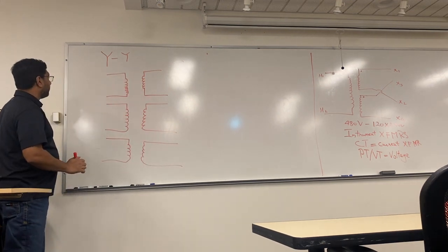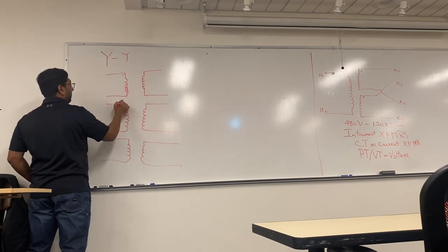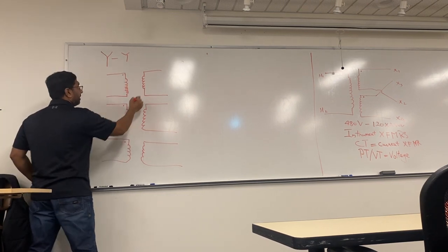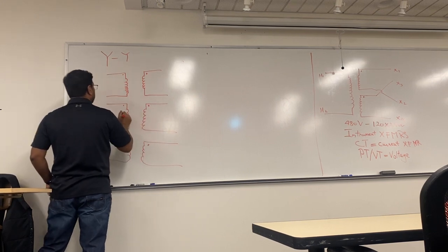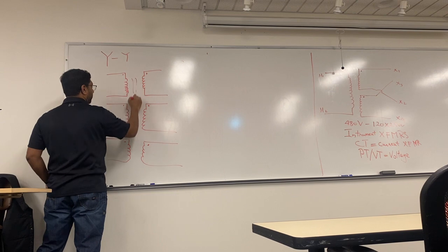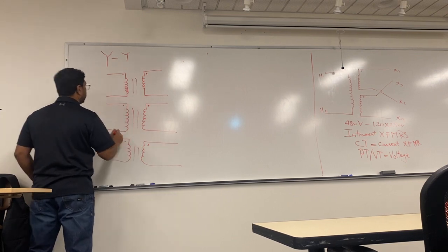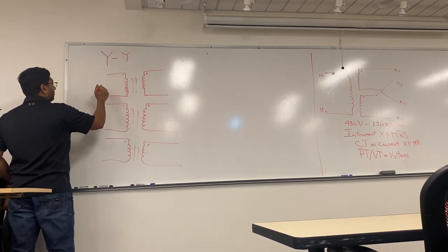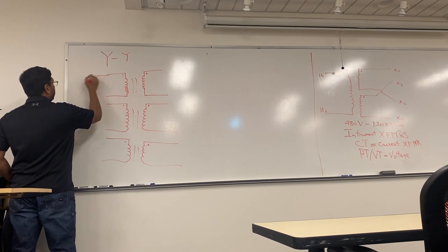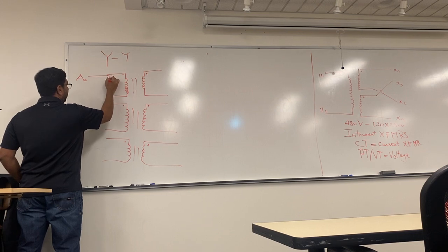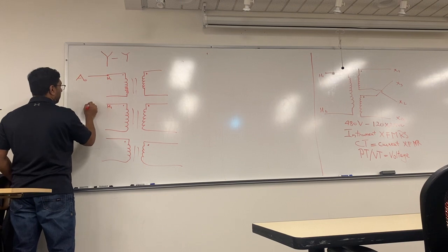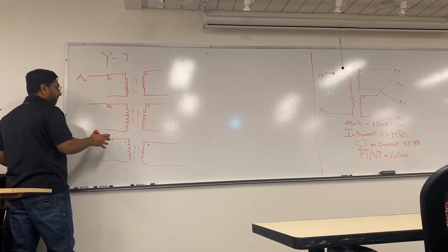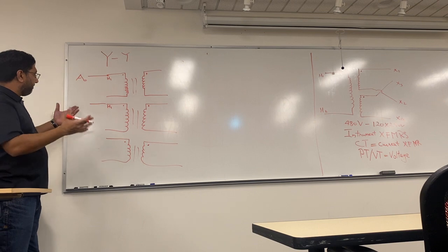So to make the transformer connection, and I have my dots here. Let's do it. So my A phase is getting connected here, and I'm going to make a distinction here by H1. This is H1. Keep in mind, these are 3 individual transformers that you are bundling up to create a 3-phase transformer.